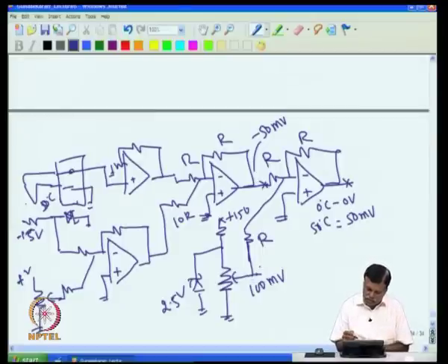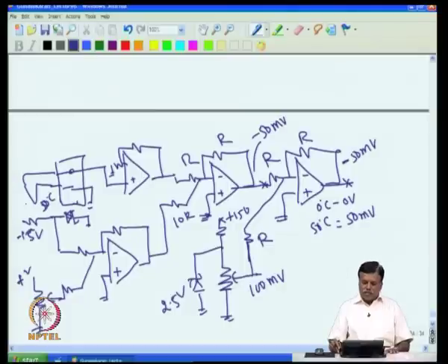So, the net result would be that you have a plus here more. So, you will get minus 50 millivolt here. If I increase this, as long as this is higher, then you will get more and more minus here. If the heater is on, and this temperature goes up, then this minus also will go up. Then as more and more minus comes, this will also come down. When the temperature becomes 100 here, this will become minus 100 and this is plus 100, then this again will become 0. So what we have done is we have generated an error voltage.